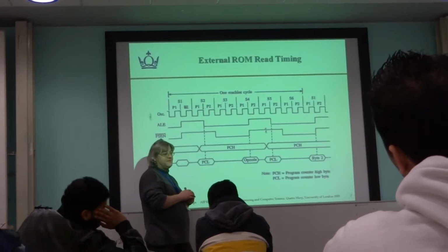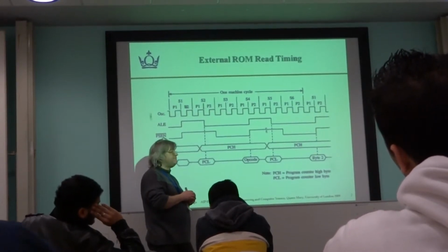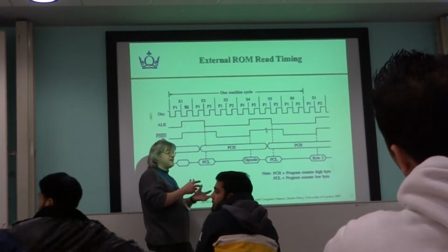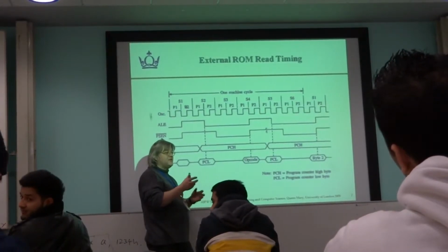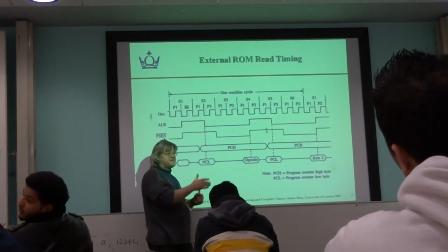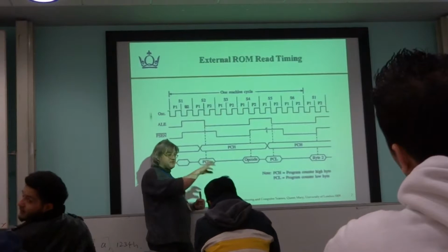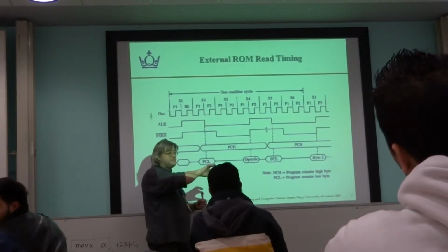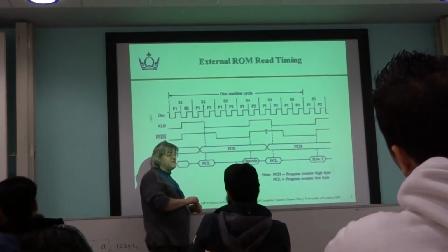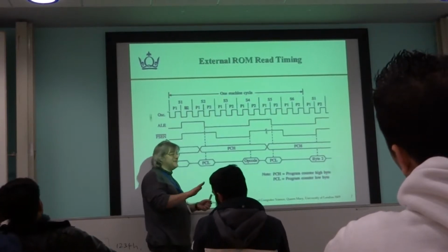I don't know why, is the short answer. It's a resonance circuit, and I think probably the crystal acts like an L and the capacitors as C, and you need something that's kind of a flow of charge backwards and forwards at a resonant frequency. But you need that charge to be stored somewhere temporarily before it flows back onto the resonator. So I think that's why, but we're getting down into really low level stuff that's not in this course for sure.